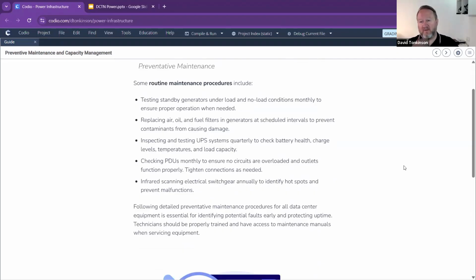Walking into a battery room, smelling the amount of caustic stuff that comes off a battery room is incredibly fun for the first time when you do it. But yes, checking the batteries are at the right voltage, putting some load on the batteries to make sure the batteries aren't worn out. Okay, the acid is still working in them and they're still basically holding electrical charge. So you put a bit of a power load across them and then see basically how long they can maintain their full voltage.